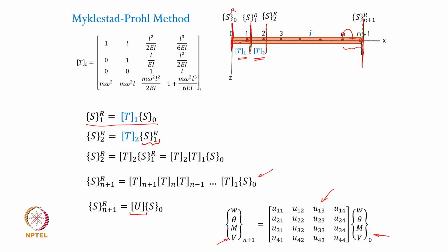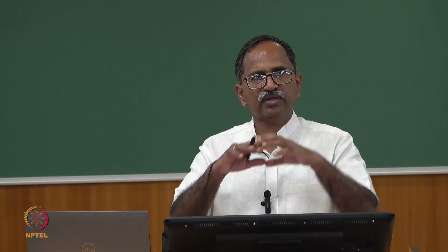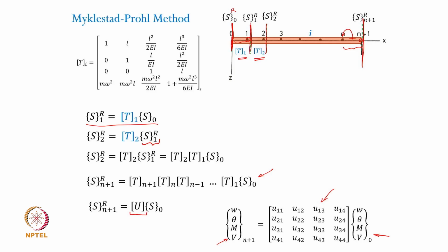And the way we did it for the previous case of the Holzer method, now the job will be to set up a frequency equation, right? This is the process that we get irrespective of whether the beam is a cantilever or simply supported or fixed-fixed. We never put any restriction on this because the deflection, slopes and all the parameters pertain to a generic deflected beam.